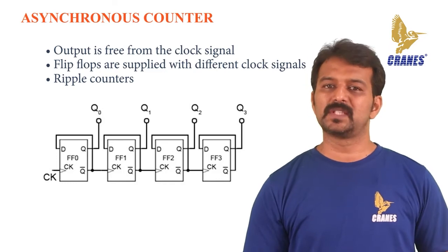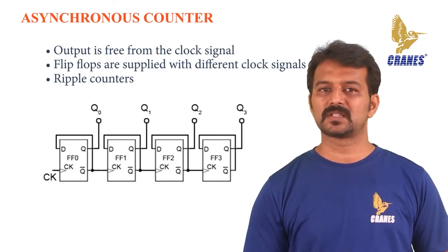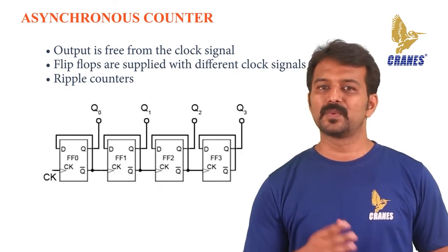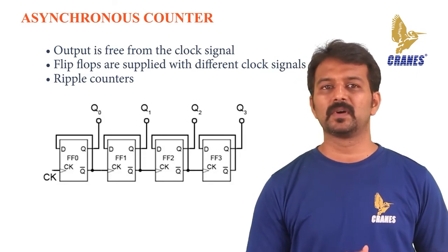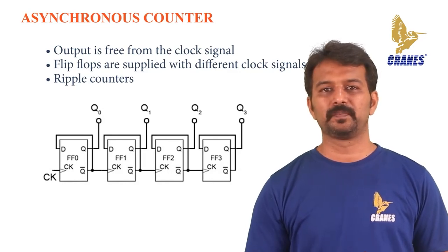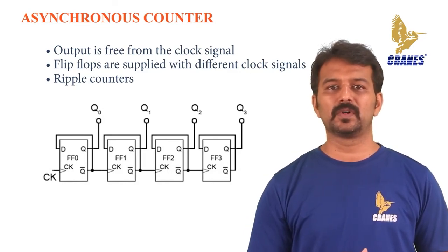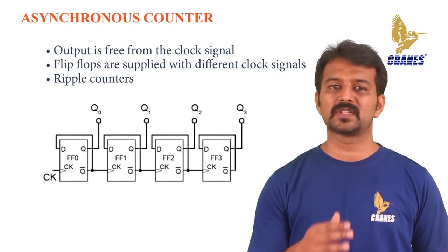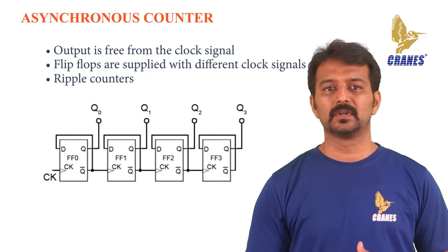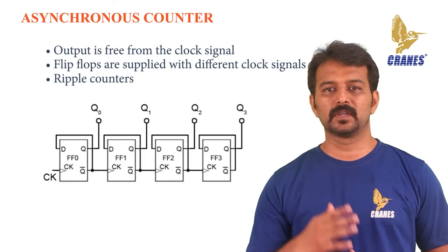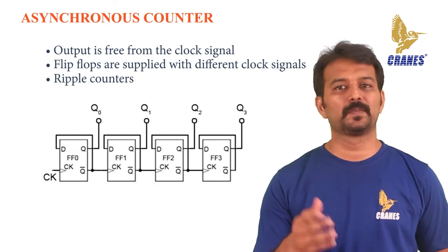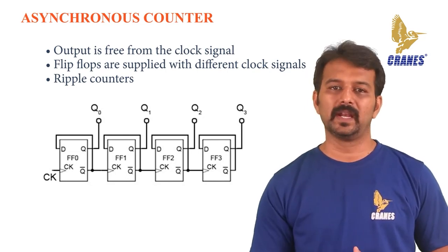The output of the first flip-flop will change when the positive edge of the clock signal occurs. In the asynchronous 4-bit up counter, the flip-flops are connected in toggle mode. So when the clock input is connected to the first flip-flop, that is FF0, then its output after one clock pulse will become 2^0. The rising edge of the Q output of each flip-flop triggers the clock input of its next flip-flop. It reduces the clock frequency to half of its applied input. The Q outputs of every individual flip-flop, Q0, Q1, Q2, Q3, represent the count of the 4-bit up counter, such as 2^0 to 2^3, that is nothing but 8.